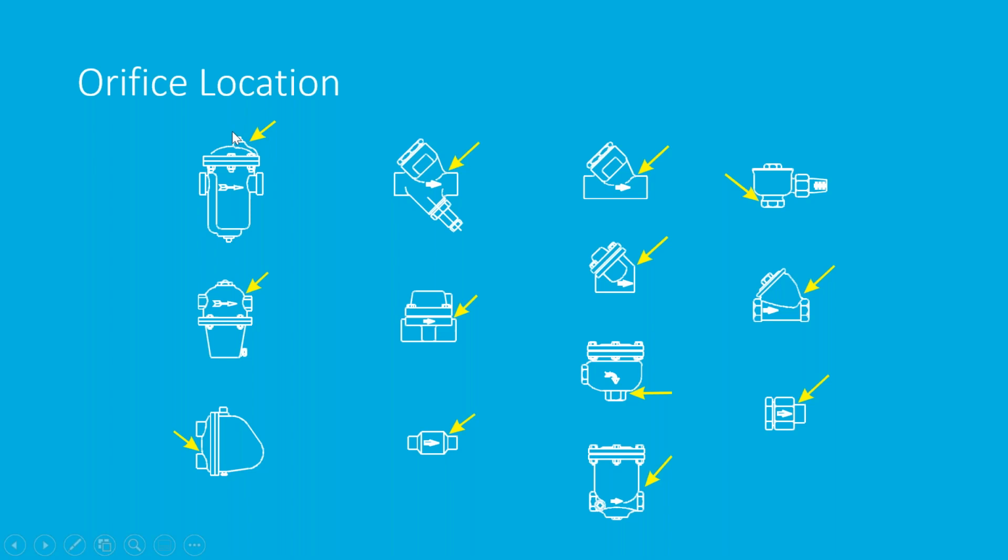So, you see your inverted bucket here. There's that floating thermostatic like I was talking about. So you have your inlet, and then you've got this curved housing, and then an outlet, fixed orifice. Here's another different style of F&T trap. And if you'd like this presentation, I'd be glad to give you a PDF copy so you've got it.